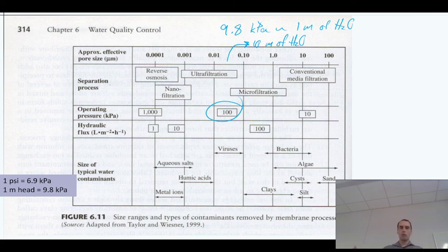And you could toggle the valves to do backwashing, and it could simply use that gravity-fed pressure, which is going to require energy, right? You have to have a way to get the water up there in the first place. But if you have that set up, then you can use that as a continuous source of pressure for the membrane itself, which removes a lot of technical challenges. So that's pretty neat, and you see that can remove most viruses, perhaps even all viruses, depending on how exactly the system was set up. And that would be a huge improvement to water quality.